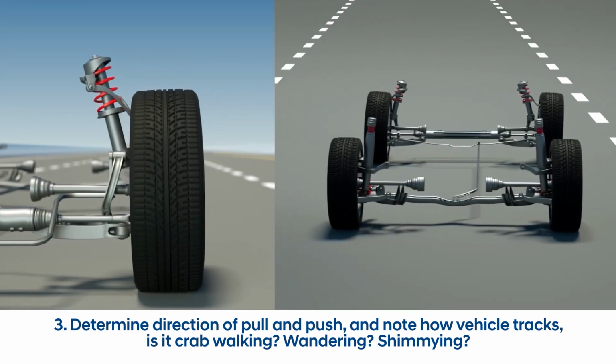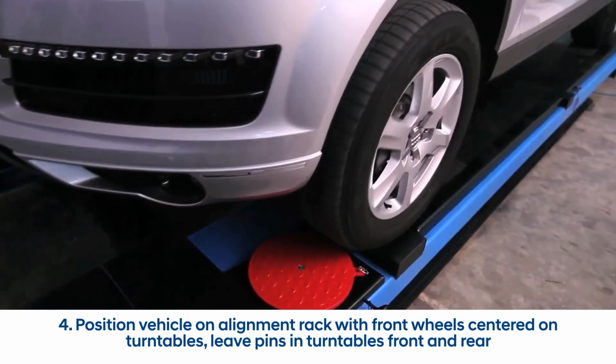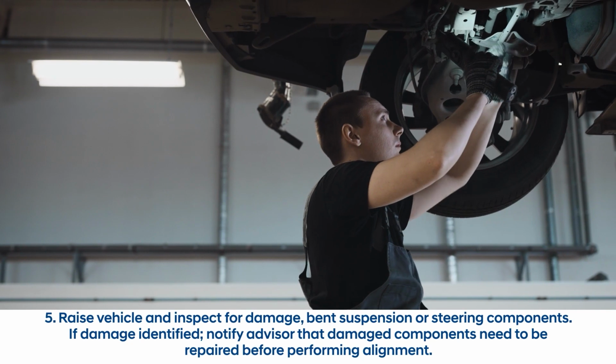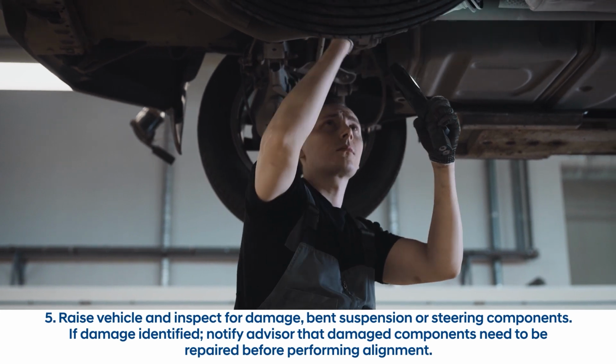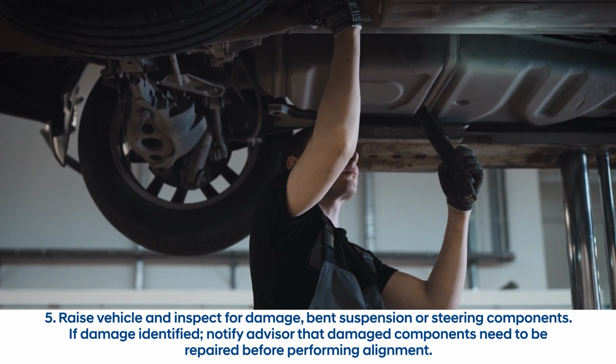Is it crab walking, wandering, shimmying? 4. Position vehicle on alignment rack with front wheels centered on turntables. Leave pins in turntables front and rear. 5. Raise the vehicle and inspect for damage, bent suspension, or steering components. If damage identified, notify advisor that the damaged components need to be repaired before performing alignment.